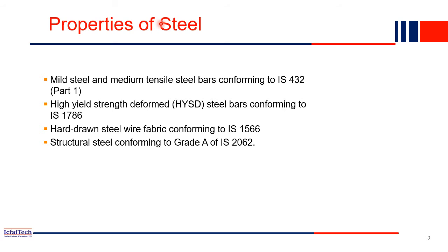Steel is very good in taking tension as well as compression. So whenever tension stresses are coming at a location in a structure, there we use steel to take care of that load. Whereas in some portion of the structure only compressive forces are coming, in that case we can use only concrete, because concrete is very good in compression.